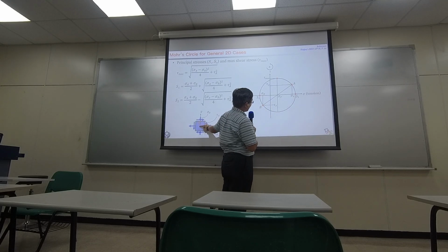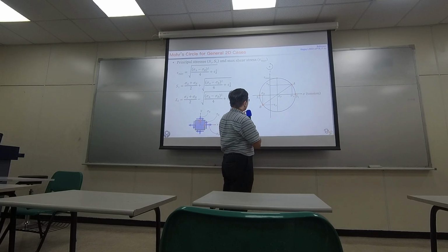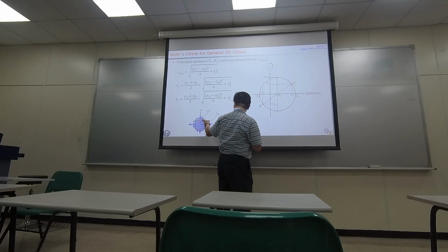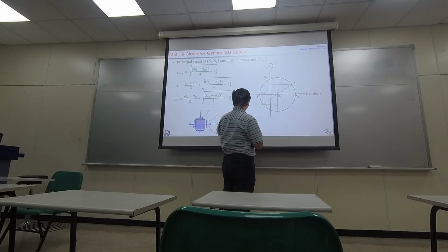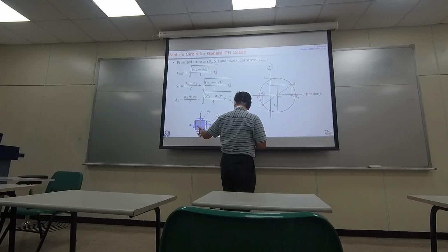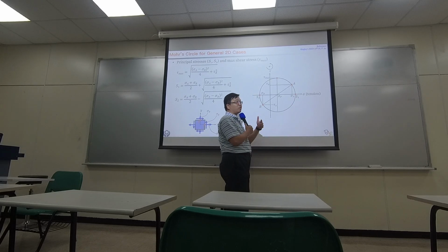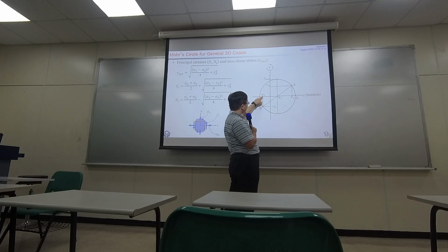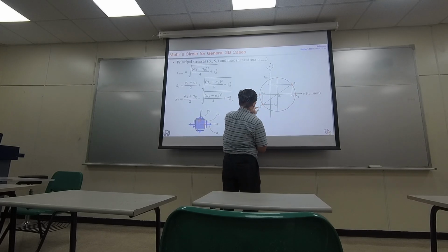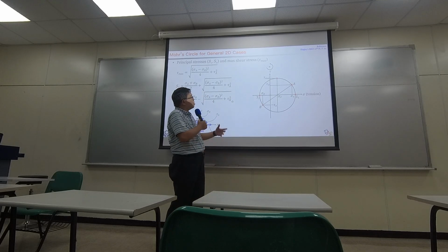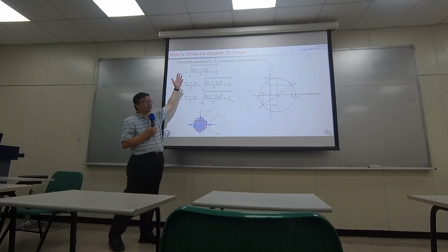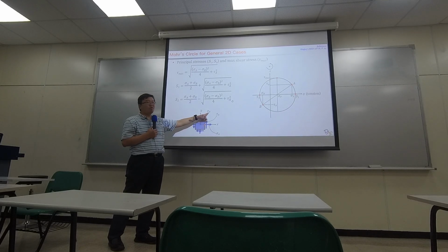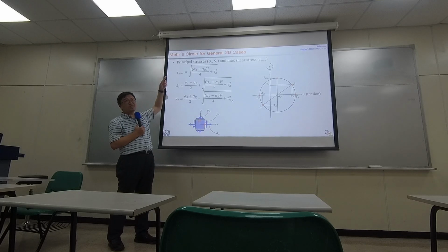In this example, for point B there is some amount of compression normal stress, and I treat it as a compression stress, so it's carrying a negative value, and the same amount of shearing stress. The only difference between this case and the earlier case is that in this one, tau B is not 0. In the earlier one, tau B is 0.